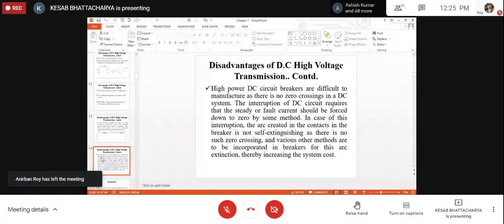That is why when you put the fan switch off, there is a spark. The associated energy is released in the form of heat and light, that is, in the form of a spark. Now, it is always preferred that the energy that has to be dealt with while disconnecting any switch should be minimum.